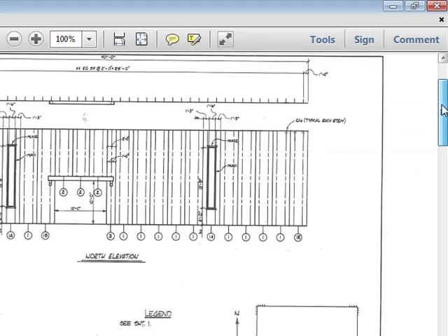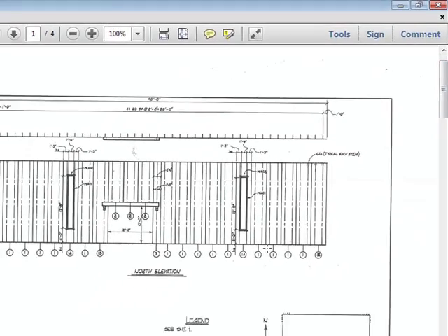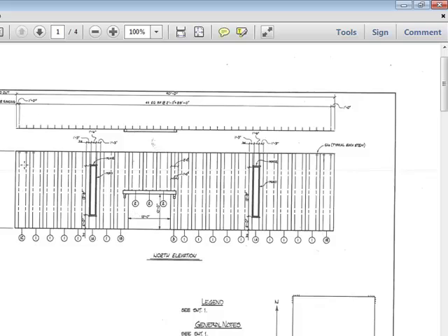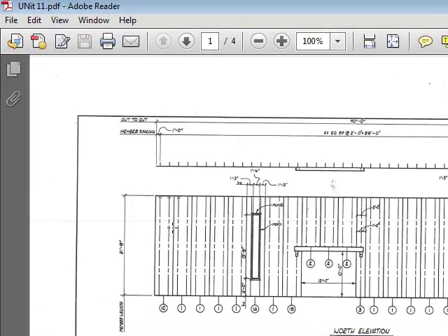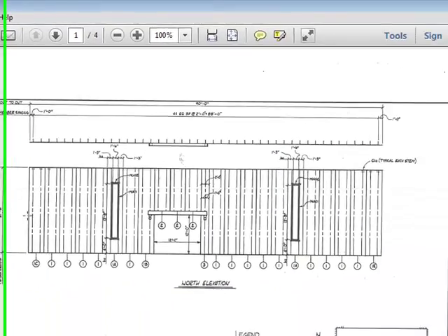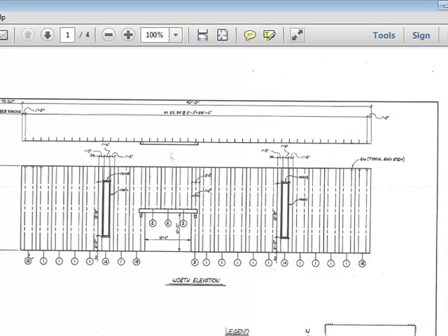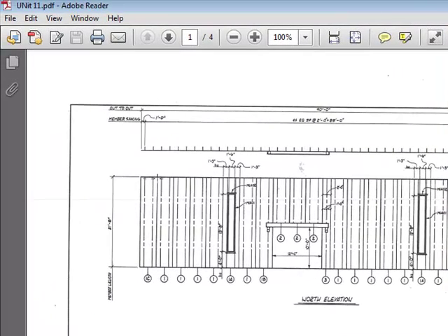And then this is the wall, if you're looking at the elevation. So these are tilt-up panels, and with the wall panels, you can see how you're looking at it again. That's one panel, and the T is on the other side. They're showing it with the center lines, the part sticking out. And then you've got your end panel here. That's going to be slightly different.